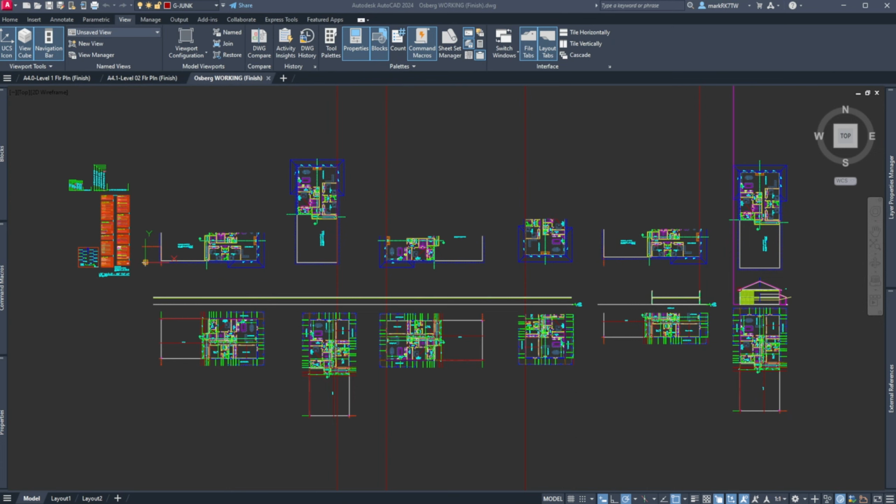And these books are free. You just can't search in the free version. So there's that vertical rise. One thing about this is that we can't have more than 12 foot 7 inches between floor levels or landings. And so we have an 8-foot floor and about a foot of floor. So we're somewhere in the 9-foot range.